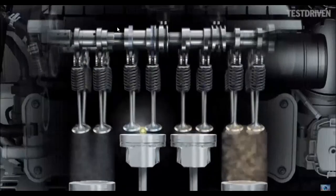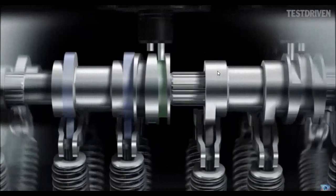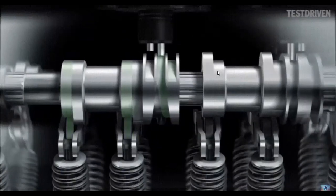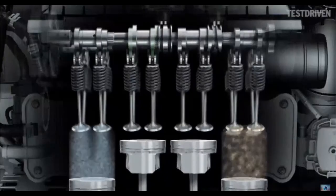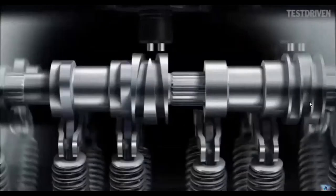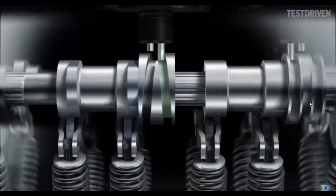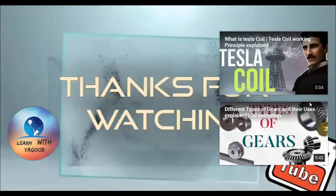As you can see, in order to have a complete combustion engine cycle, the piston has to perform 4 strokes. This means that one engine cycle takes 2 complete rotations of the crankshaft, 720 degrees. The only stroke which produces torque energy is the power stroke. All the others are consuming energy.